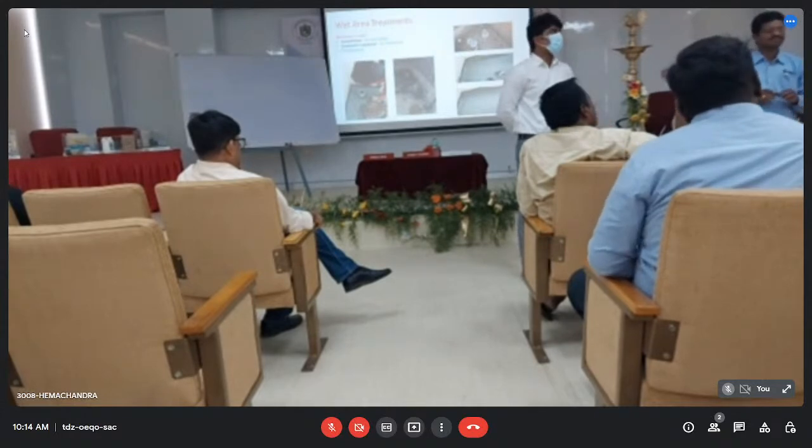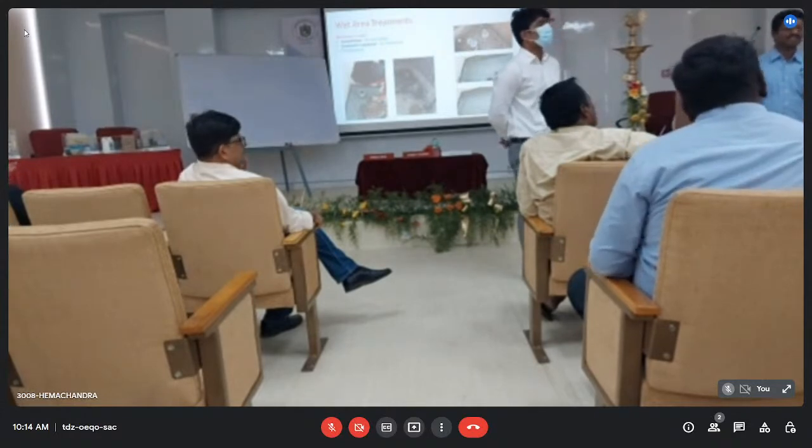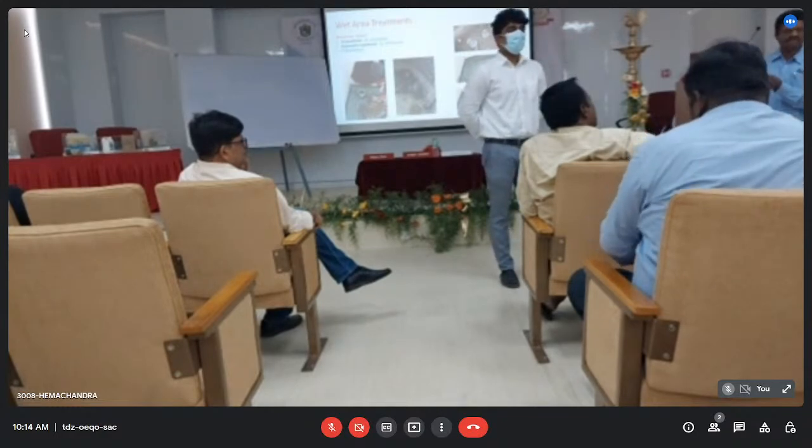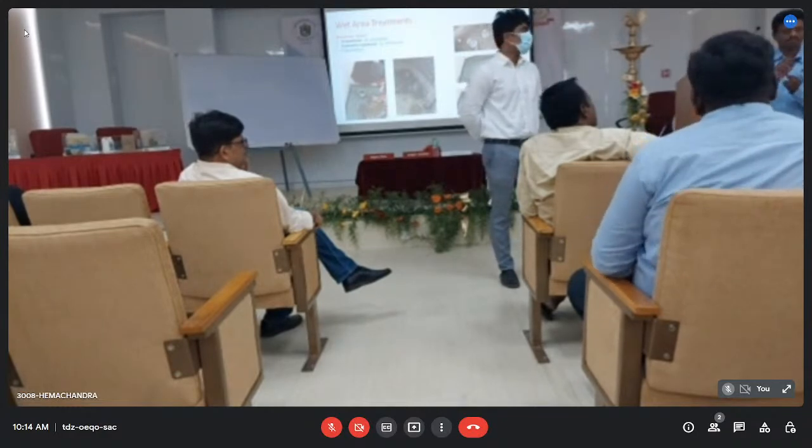Any grout with free flow grout. Free flow grout you can go. Any brand you can go. It should be free flow. If you pour here, the grout should touch the end point.